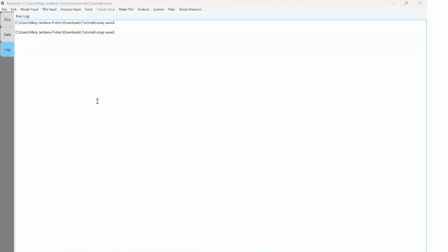Next, we need to define the model domains. For this model, let's define an aquifer system with 3 domains. I should note that in practice, you would define your domains based on a conceptual model. And for complex projects, you'd likely use data management tools like Excel or GIS to organize and transfer data. But for this tutorial, you can simply copy the domain details from my screen.